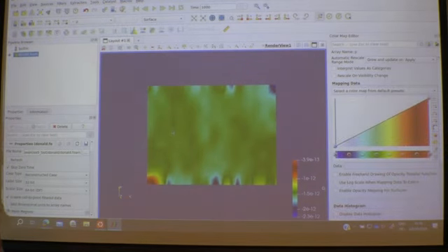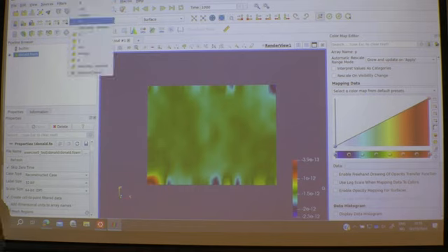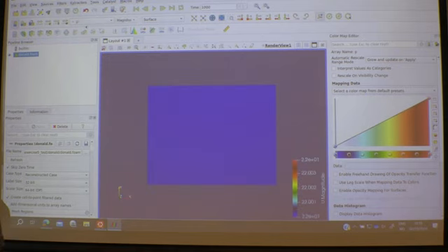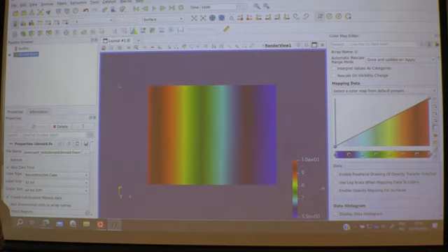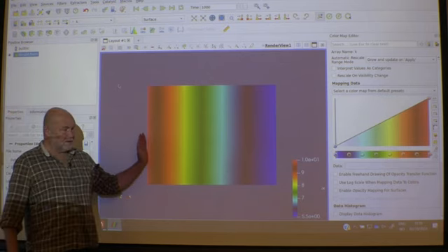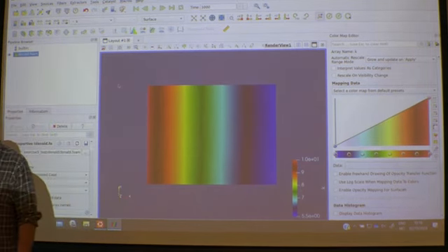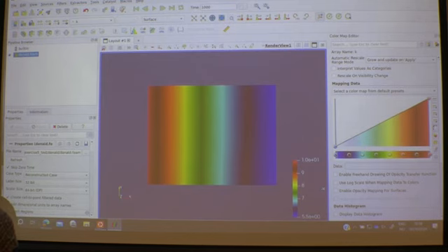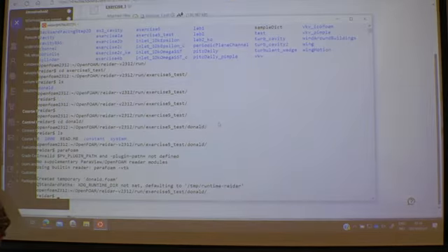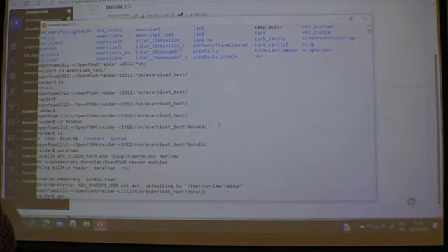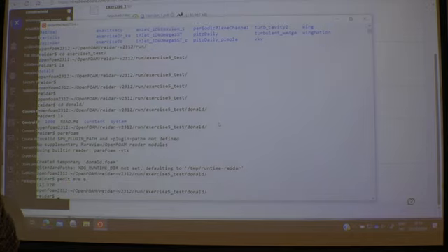We got constant pressure all over the place, we got constant velocity all over the place, but we still had the turbulent quantities. And here the question was, what do you send in? Whatever you send in is going to decay down to 0 in the end anyway. And then I thought I had found some very nice setup here, but it turned out to be wrong. Let's see now. Gedit, the 0 directory. Let's take K for instance.